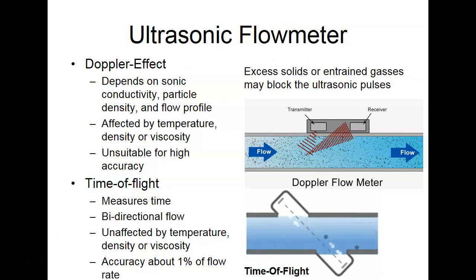Then we'll have what we call ultrasonic. These work on what we call the Doppler effect. The Doppler effect depends on sonic conductivity, particle density, and flow profile, and is affected by temperature, density, and viscosity. It's unstable for high accuracy, so we wouldn't use these for extremely high accuracy, but it gives us a rough range. It's like in electronics: our math is perfect, but our components are not, right? And if we can live with that tolerance, then we're okay.